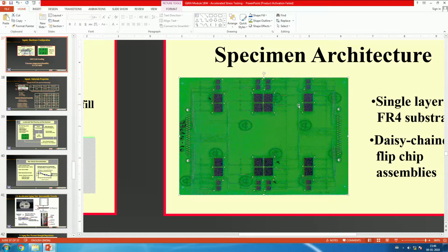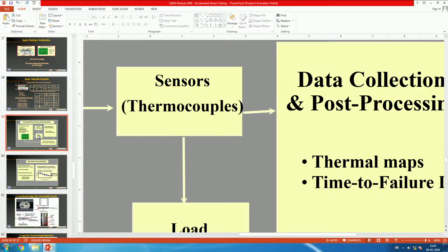So we were studying some specific underfills. Some boards had underfill A. I'm not allowed to name the underfill. So some had underfill A, some had underfill B, and some had no underfill at all. The no underfill boards we used only for thermal cycling testing, because if there's no underfill, there's no question of swelling of underfill and applying stresses. So for this study, the no underfill boards were not necessary. But for thermal cycling, we had some boards that had no underfill. So today, I'm not talking about the thermal cycling part of the study. I'm only talking about the moisture humidity part of the study. Okay.